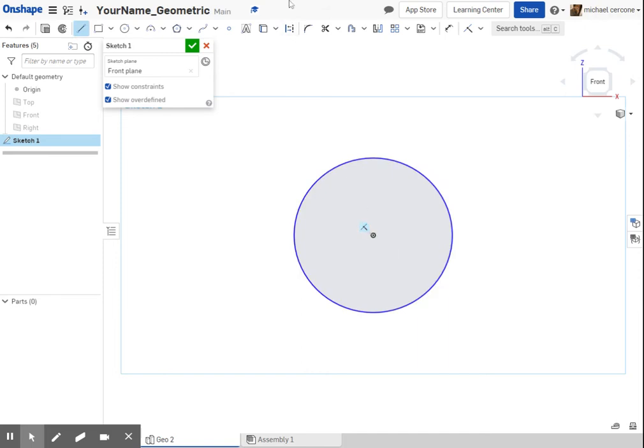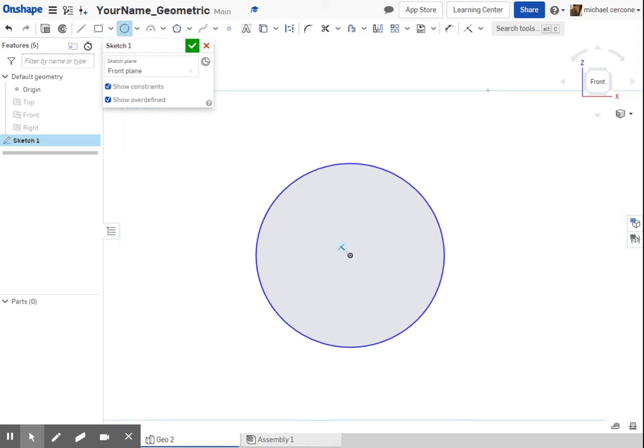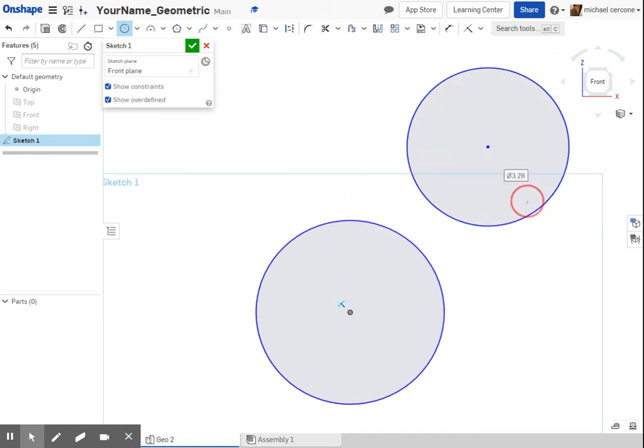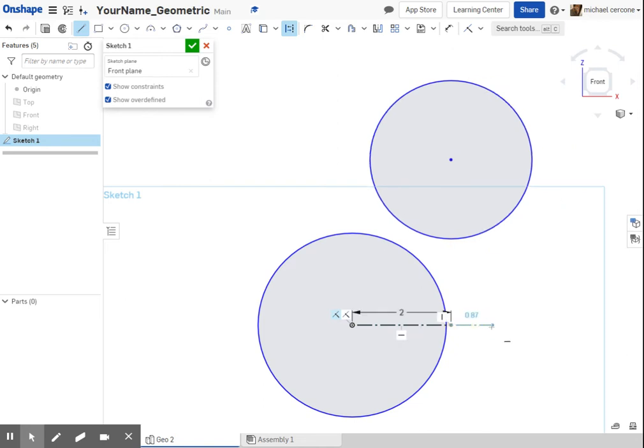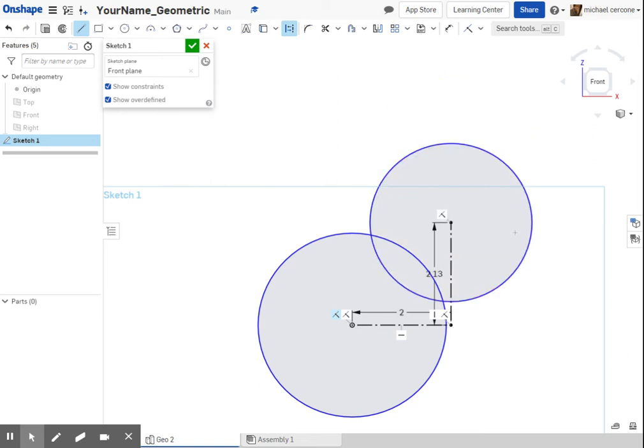and looking at this right here, I can see that I have a 2-inch dimension that goes over, and then a 2 1/8 up to the next one. So what I'll do here is just draw 2 lines to get this into place, or I could just draw another circle floating somewhere over here, and I could define it later. What I'll do though is draw these construction lines, and I'm going to define this one at 2 and this one at 2 1/8, so 2.125, or 2 plus 1 divided by 8. That will get those into location.